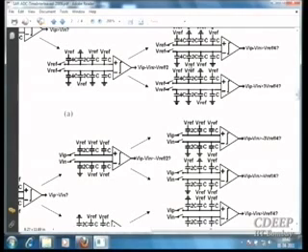VIP minus VIN. Okay. You want to compare VID with Vref by 2. What is VID? VIP minus VIN, meaning the voltage at the positive terminal minus the voltage at the negative terminal. Now look at capacitive division. On the upper side, what will you get here? 3 Vref by 4, right?